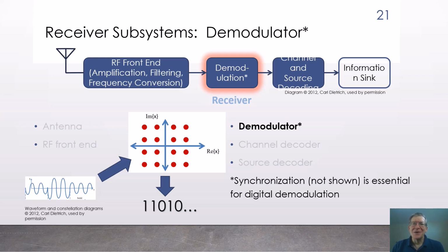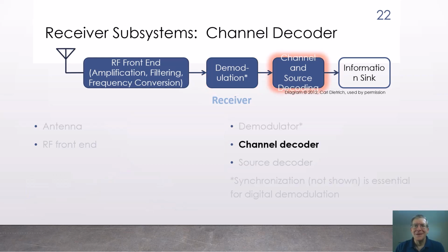For now, we are ignoring synchronization, which is a complex and challenging yet essential process, particularly for digital receivers. Precise synchronization is needed to enable the receiver to match the transmitter's frequency and phase within a narrow tolerance that enables the receiver to demodulate the signal accurately. Synchronization is also essential because it allows the receiver to keep track of transitions between consecutive symbols and bits.